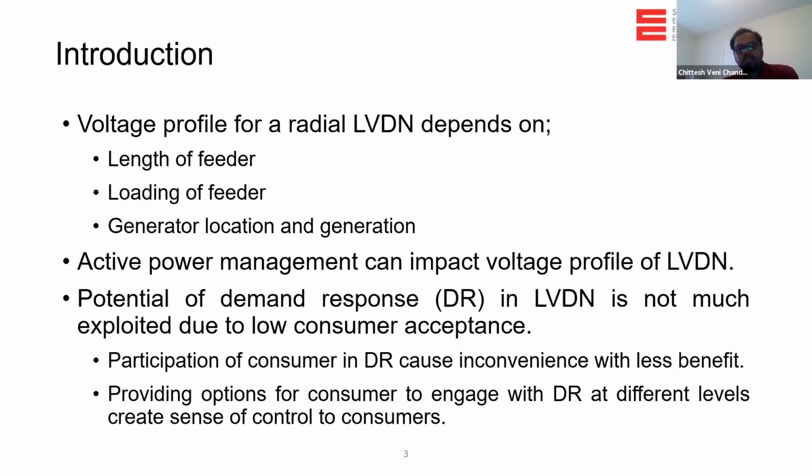So the first thing we were looking into is we wanted to use some method to control the voltage at the end of the feeder. We considered both over voltage and under voltage. The over voltage scenario is when there is more generation under lightly loaded condition, so we want to do curtailment of generation, and for the under voltage scenario we wanted to curtail load. In order to curtail load, we wanted to use demand response.